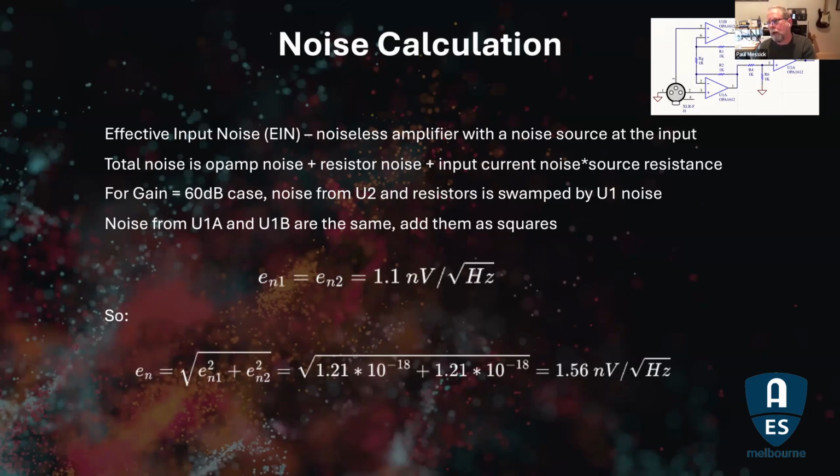One of the cool things about these sort of amplifiers, by the way, a quick aside, is the noise of the amplifier itself goes down as the gain goes up, which is very cool for making things with a lot of gain. If you think about it, if we set RG to, and it shouldn't say 1R there, that's a mistake, but if RG is open, then the resistors all add up something and there's a bit of noise there.